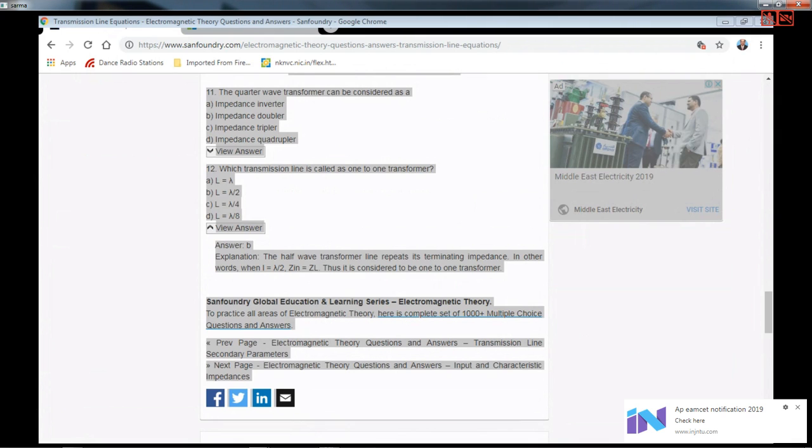Of course, for VSWR measurement, we need to find this, and we are not looking at the location; we are looking at the maximum value of this voltage wave. So whether it happens here or here, it doesn't matter. That's how the repetition of the values is going to give you less error. That's why VSWR is always chosen for the measurement part.